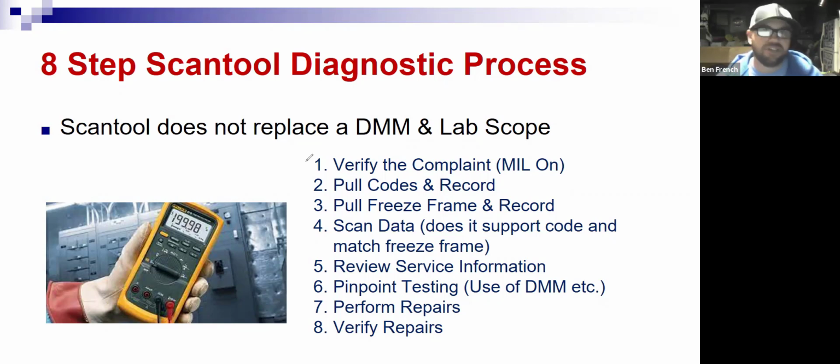So whatever you're trying to diagnose on a car, the first thing's always verify the complaint, right? Imagine if a customer came in and they said, hey, my car has a vibration, right? You would go for a test drive and see if you could feel the vibration, thereby verifying the complaint. Yeah, there is a vibration. For us in this class, we're doing scanner diagnostics. So normally the person's going to complain that the check engine light, or the MIL as we call it, the MIL is on. So we verify that that light is on.